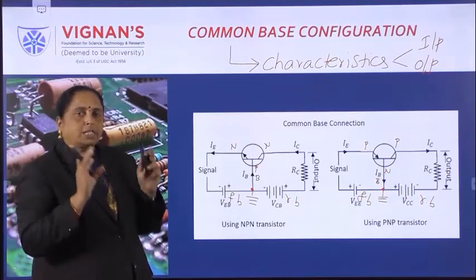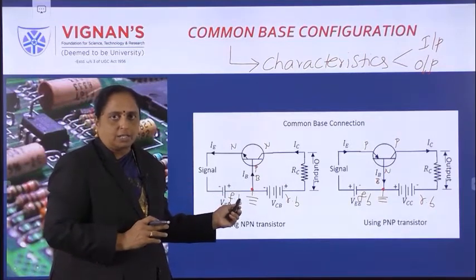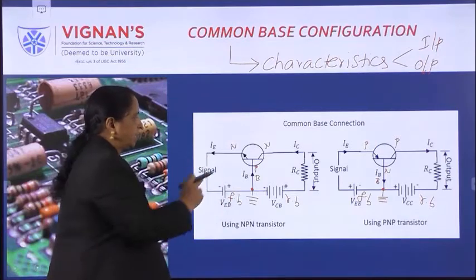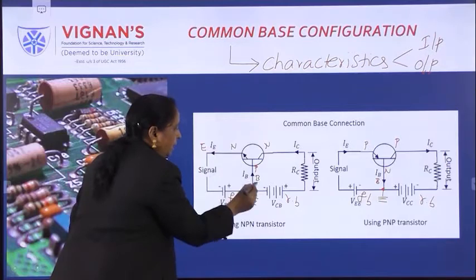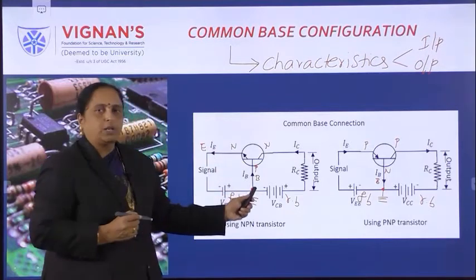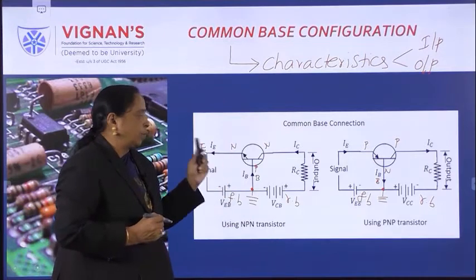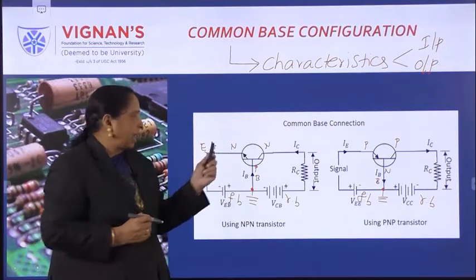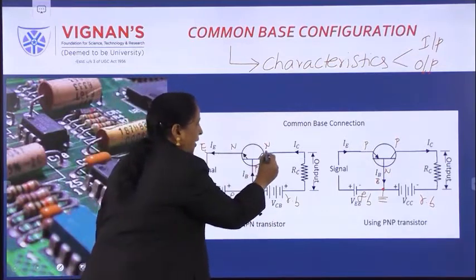So now the experimental setup circuit is different from this normal configuration. So what is the input voltage here? This is emitter terminal, between emitter and base, one voltmeter you are going to connect, VEB, and the corresponding current can be noted by using ammeter, IE. Similarly, what is the output voltage we can connect? Between collector and base.